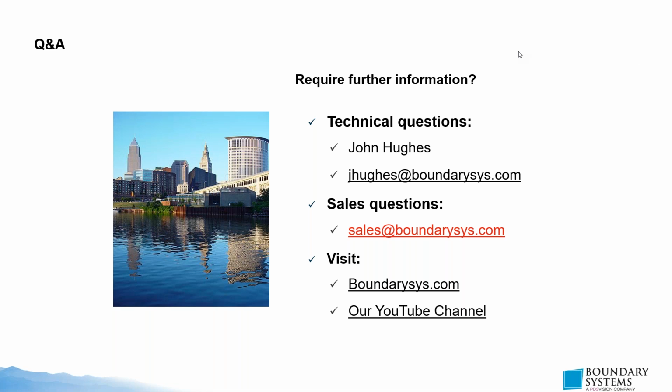Let's see. You should be able to. I have not tried to extract that silhouette surface, but probably I'd say split your blocks, and then it's easier to copy those specific surfaces, whether it's the core and cavity, and you've got all that other geometry, then you can copy and extract that. So I'd say yes, you can do without doing the blocks, but for the extra less than a minute it took, I see more advantage of just creating the blocks and then sharing that geometry as well.